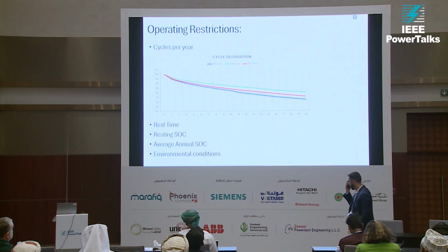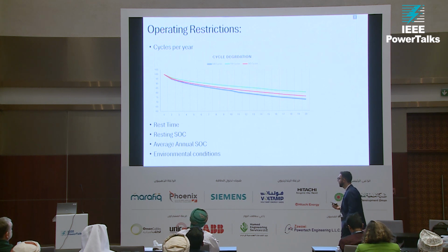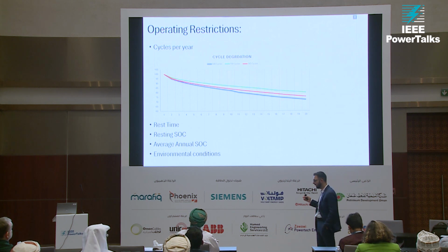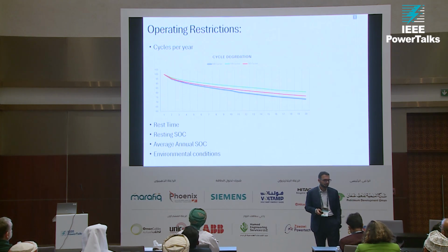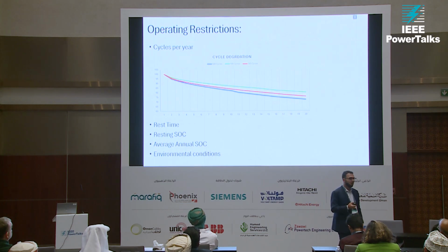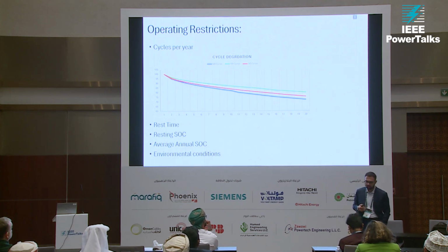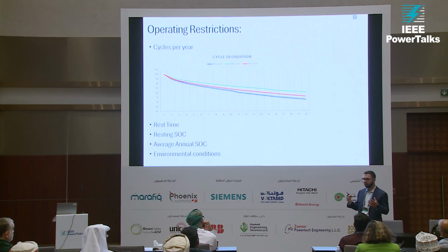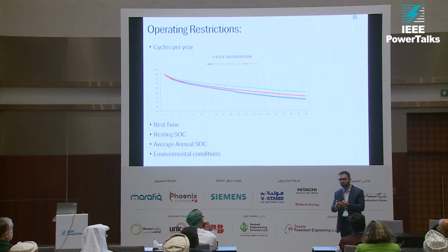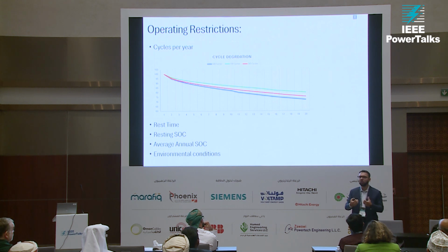Other operating restrictions, we touched on some of that, are resting time and resting SOC. We talked about resting time, so I'm not going to touch on that, but let's talk about resting SOC for a minute. Resting SOC is when you charge your battery, and EVs are a great example. When you charge your battery in an EV, it's better not to charge it to 100% and leave it for a few days at 100% charge, because when you put energy in a cell, you're adding stress to the structure. So you want to relieve that stress as fast as possible. You don't want to be stressed at 100% for a long period of time.